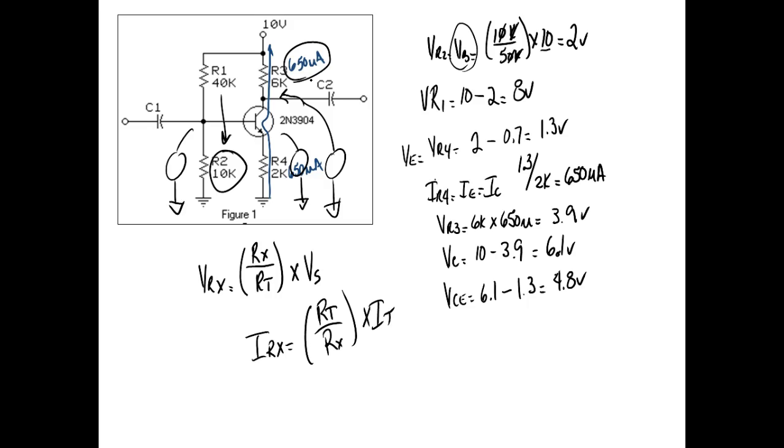What else do we need to solve for? AV in this situation is going to be equal to 6K over 3K, so this is going to have a gain of 2. It's a very poor amplifier, but you have to understand these worksheets are not intended to be good amplifiers. They're just in here to get us to learn how to do the math.